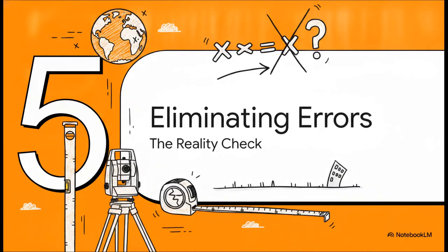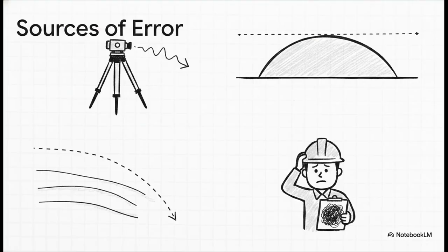Section 5. Eliminating leveling errors. The reality check. Flawless math is wonderful, but as we know, physical reality always likes to introduce some errors. What are the natural antagonists trying to ruin our perfect horizontal line? Well, first, the instrument itself might be misaligned. Then there's the Earth's curvature. Over really long distances, the planet physically drops away from our straight line of sight. We also face atmospheric refraction, where the air literally bends the light entering the telescope. And of course, there's always human error, like simply writing down the wrong number in the field book.